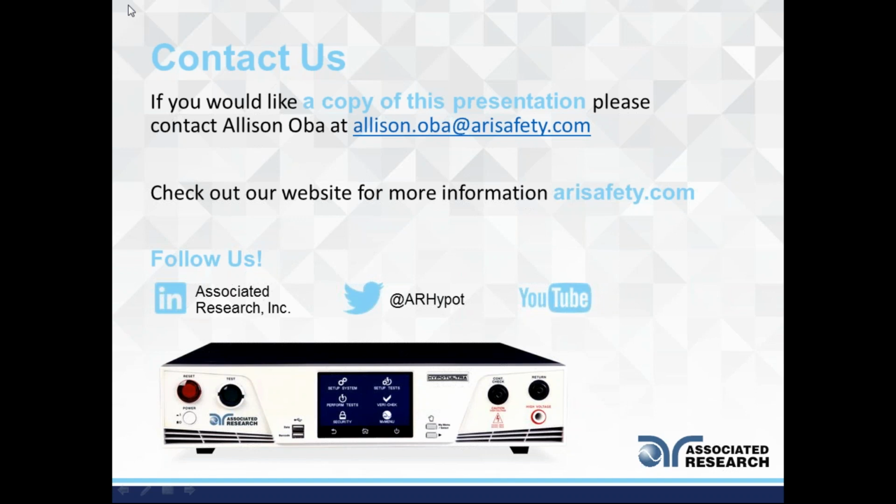Sure. So like I said, this webinar is split into two parts, and we had decided to talk more about setting trip limits in the next part, but I'd be more than happy to briefly discuss how the current high and low limits in a Hipot tester can be set. So for example, the way we usually recommend our customers is to take, for example, 10 samples or a number of samples of a product and perform a Hipot test on those products.